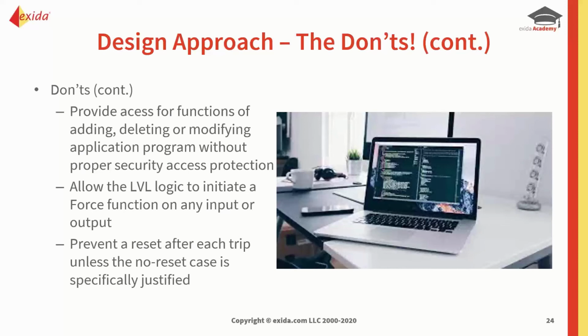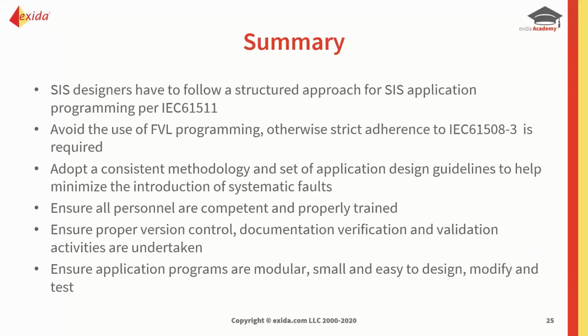We should make sure that there is a reset after each trip to make sure that everything goes back to the startup condition. Unless, of course, the no reset case is specifically justified. So this is very important. We should make sure we start from a known good point. So if we've had a trip, even if only part of the process is tripped, we need to make sure we do a proper reset on that part so it starts up in the right condition. So these are some of the don'ts.